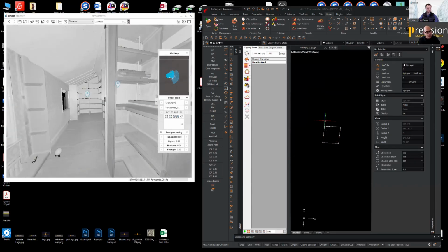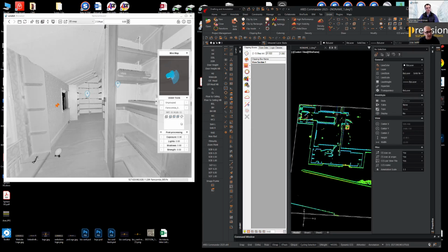If we want to take this section to cut through, let's say halfway through where this window area is, we use the tool which is translate view section. We're inside of our thing, and if we translate the view section by clicking in the box, the view section automatically navigates down to position the center of our sliced section at the point where we've taken our information.